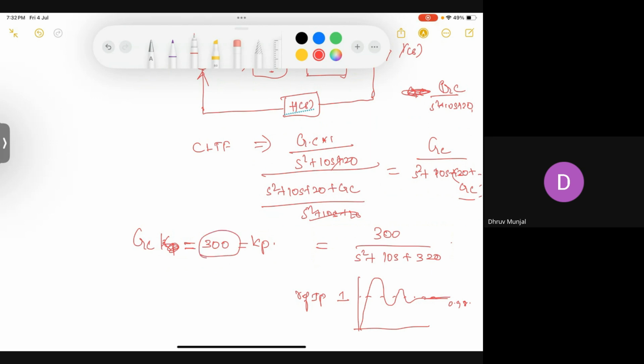So for this gain, likewise, you have to tune the gain, do a trial and error method to make the gain come to a proper number where your output response will be behaving in the required way. That's how we design the controller. If you do it by hand, it will be tedious.